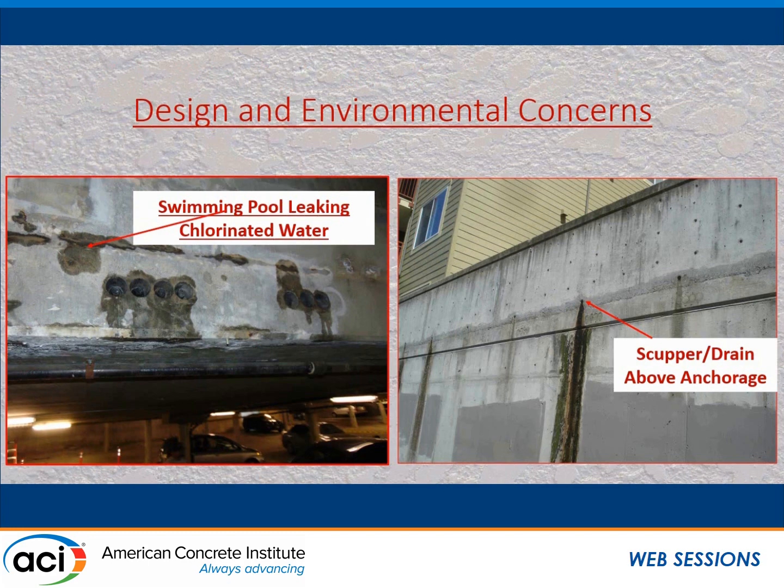Another thing that happens, and this was through another investigation where they knew they had some post-tensioning problems, was on the photo on the right, wrong or indifferent, they've got a swimming pool above. Well, obviously a post-tension slab is supporting the pool, and then where the leakage occurred, which shouldn't maybe happen, was right over the anchorage. Now, in this particular case, it didn't appear to cause any corrosion or damage, but we opened it up, cleaned it, prepared it, and regrouted it.